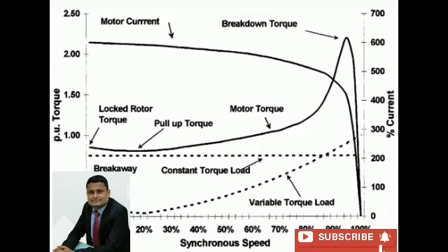Stator copper loss, length of mean turn. Empirical relation: LMT, length of mean turn, equals 2L plus 2.3 tau plus 0.24. That means L is the go conductor, 2.3 tau is the overhang, L is the return conductor, and 0.24 is for connections. So L equals the gross length of the stator, tau is the pole pitch, and all dimensions are in meters.